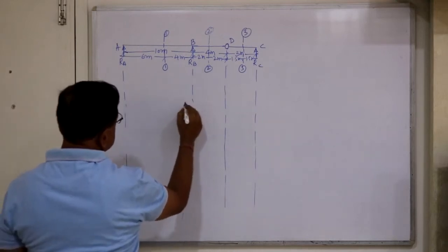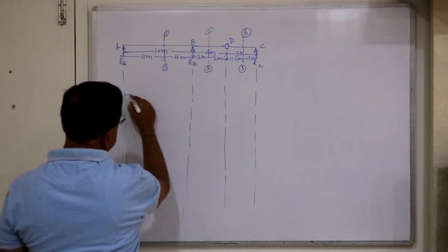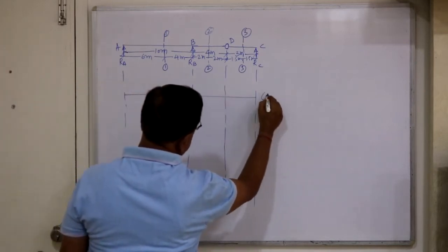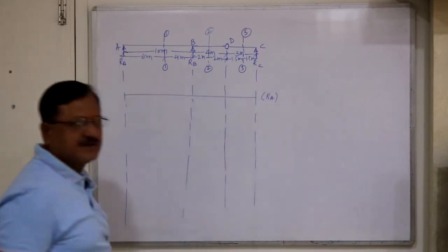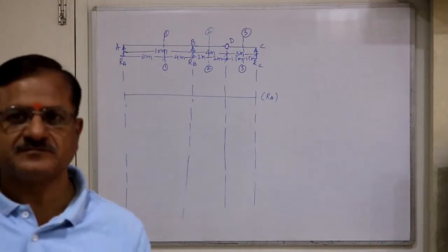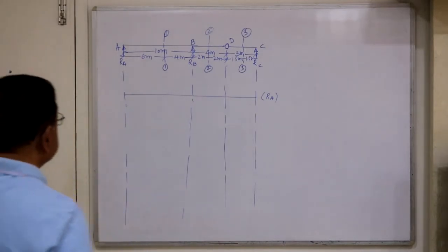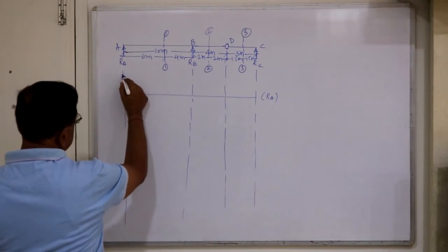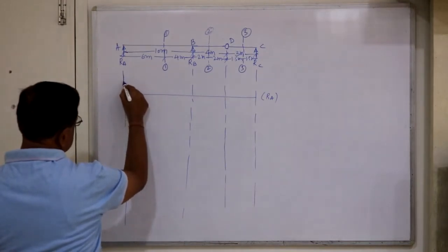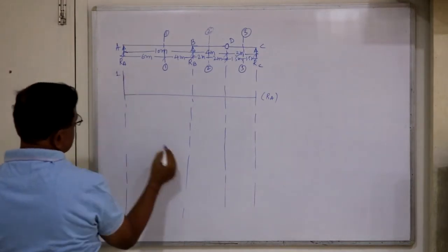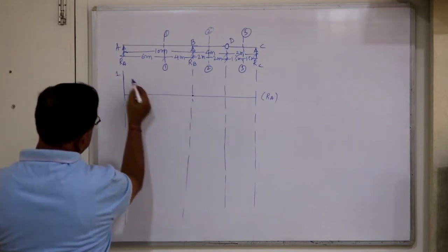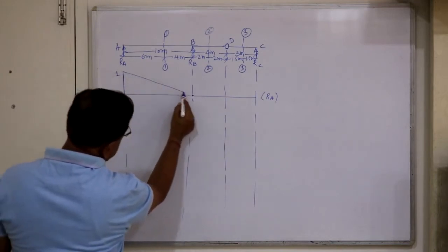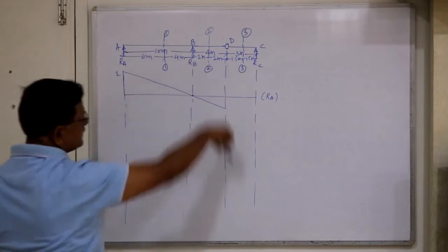Say let's first do RA, ILD for RA. Now RA means lift A through 1 unit. Lift A through unit, this is 1. And deflection here is 0. So draw a straight line up to the hinge. So this hinge will go down.